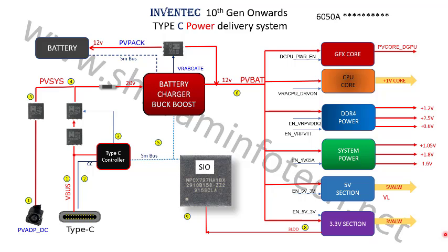So in this session, we are going to learn about the power sequence of the Inventec boards. The Inventec board numbers start from 6050, and currently most of the new generation laptops, especially in HP, the 6050A board is very common. This make is called the Inventec motherboard. We have seen Compal motherboard, Quanta motherboard. This Inventec is another manufacturer who's making the motherboard.